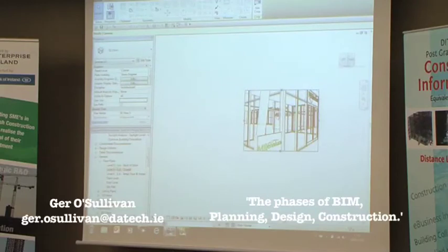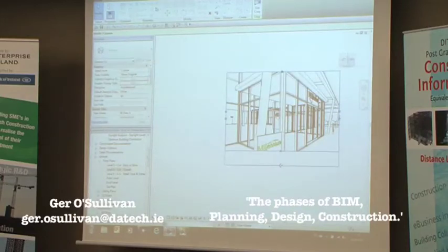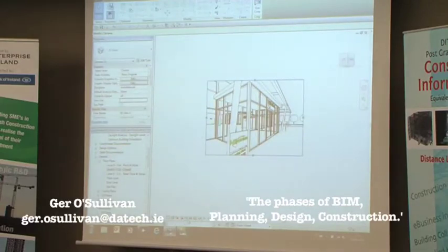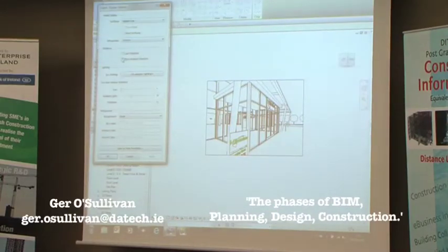Again, live information. We can very easily crop or expand the crop region here so we see more of that porch area, like that. And then we can start enhancing it even more by turning on shadows again. I've done that a few times, so I'm not going to. I'm going to change the shadow option here, and we might use something called ambient shadows. They're not true shadows, they're just basically applied to objects where they meet other objects. If something is circular or curved, you'll get a shadow effect on it, so we can apply that.